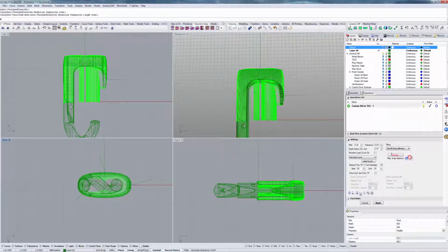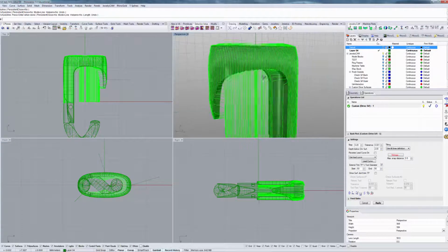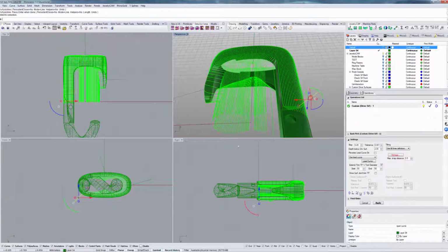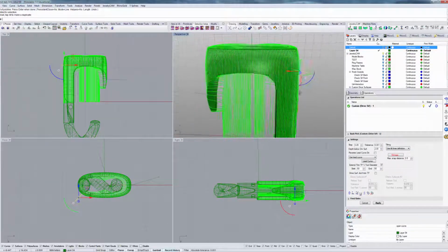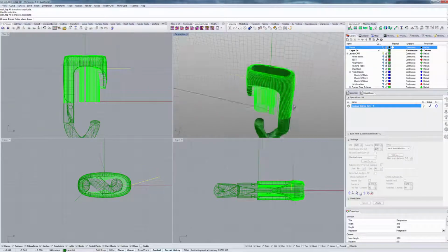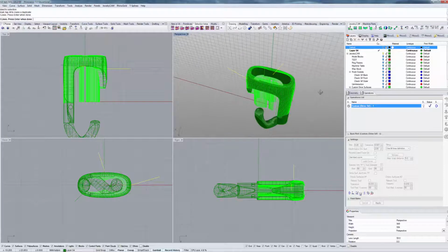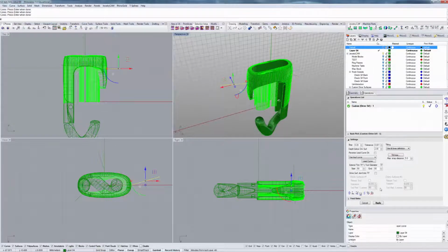We set the snapping distance. This is important because if our lines are a little bit away from where they need to be, JewelryCam will have a hard time finding them. So we need to make sure that we have our snap set to an accommodating distance. So I'm going to set that to 5. And for tilt lines, I'm going to specify 1, 2, and 3. And press enter. Click apply and recalculate.